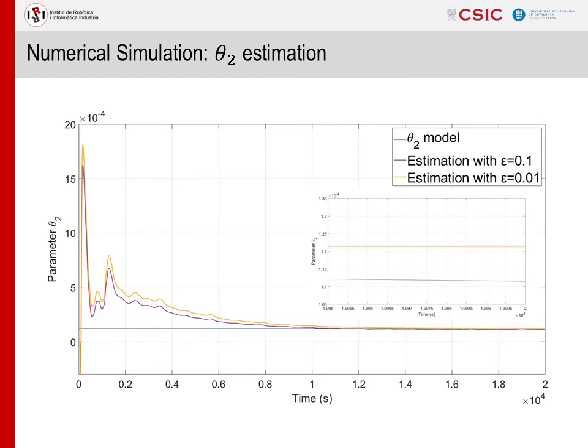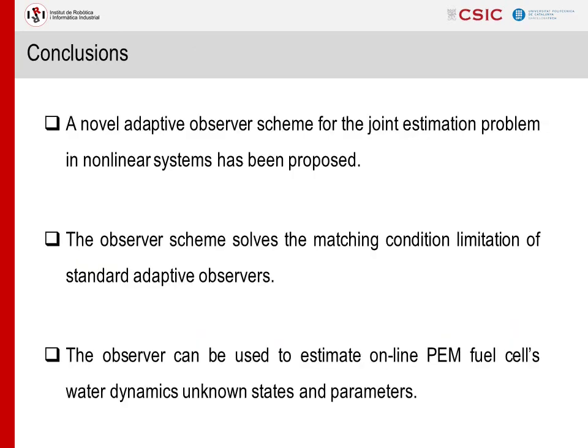As a conclusion, this work has presented an adaptive observer for the estimation of PEM fuel cell water dynamics unknown states and parameters. It has been shown that the considered fuel cell model does not present the relative degree condition required in common adaptive observer techniques, and a modified strategy based on a high-gain observer has been proposed. The results of the observer have been validated through a numerical simulation.